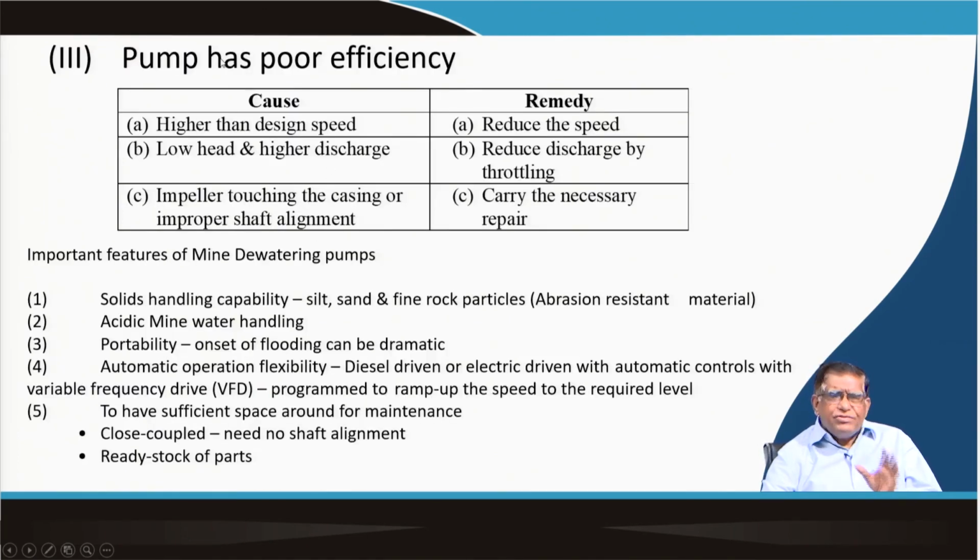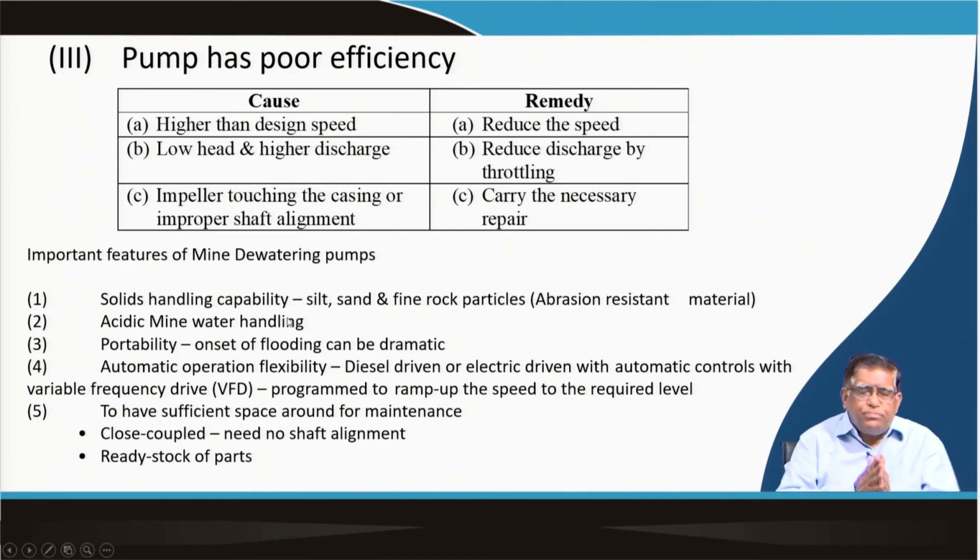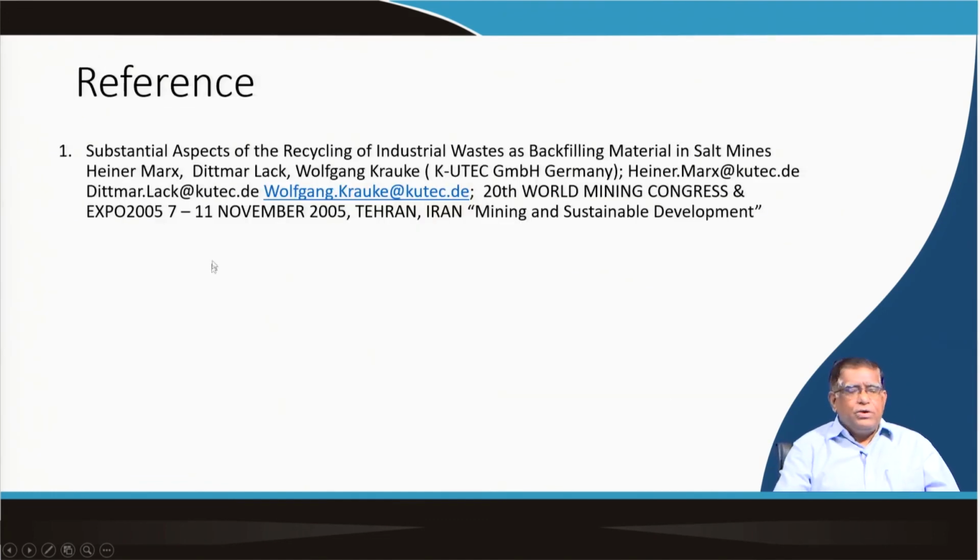Some problems may be of efficiency. Efficiency means more power is getting consumed, so you check whether you are running it at the proper design speed or not, and whether the head and other things are designed accordingly or not. A detailed investigation can be carried out, and you can get into how your pump can be running well. So in a nutshell, this is an introduction; you will have to collect information, study its working, and only then can you do it.